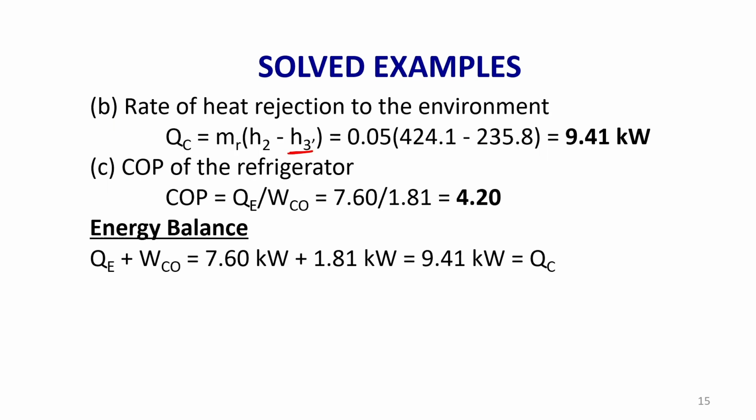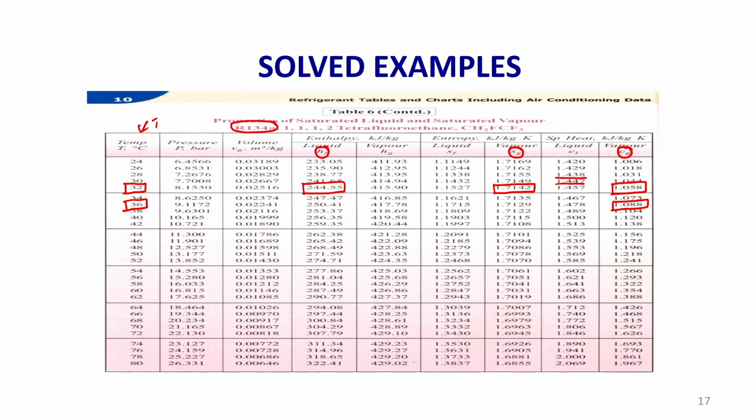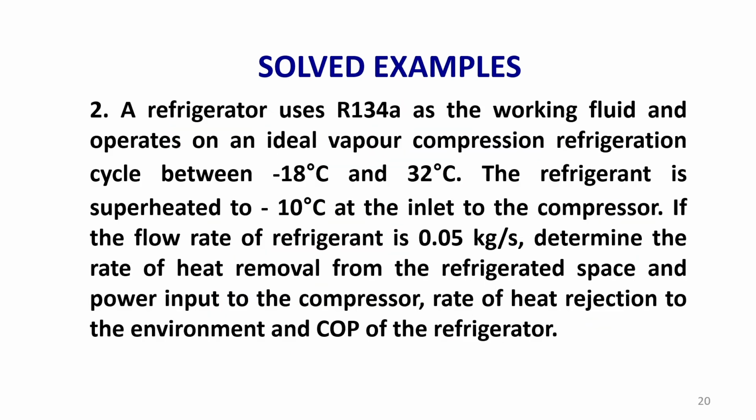So, we can calculate the COP. Again, the energy balance you can do: the desired output, that is the refrigerating effect, plus the work power required to drive the compressor will be equal to the heat rejected by the condenser. So, the next one, the second one, I have taken the same condition, evaporator temperature, condenser temperature, refrigerant is superheated,